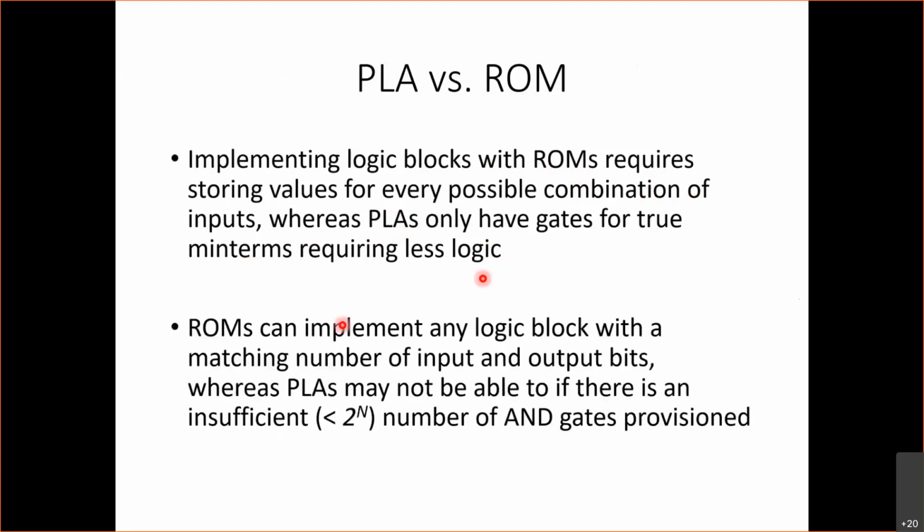PLAs require less hardware than ROMs because a ROM stores every possible output, whereas a PLA will only store the output when the case is 1, or if it's a PLA that does product of sums, you only need to program the cases where the output is 0.